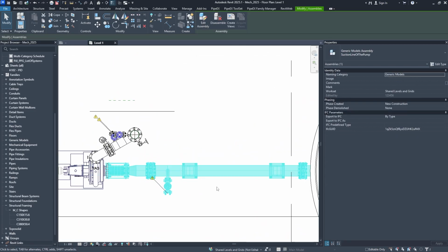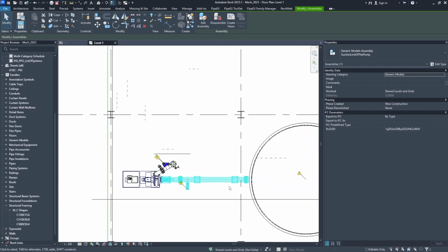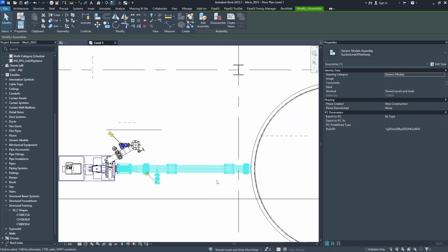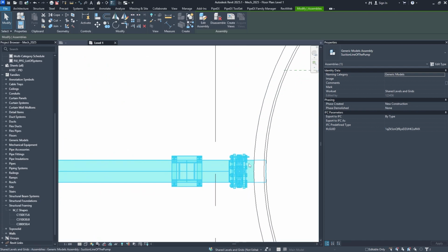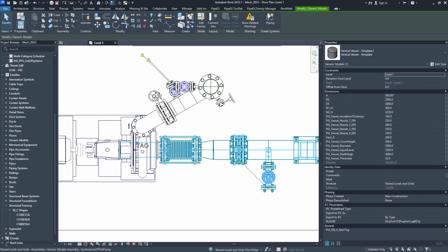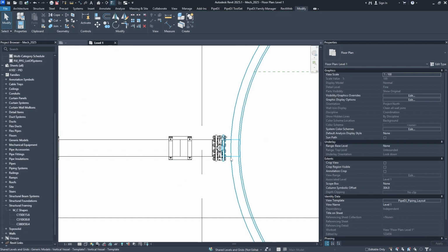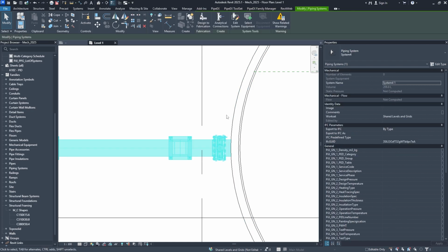Then what you can do for this assembly, you can add a reference, for example a comment, and you can add a remark on your piping layout, just not to show all the dimensions in this view. Because here you can use, for example, the nozzle of the equipment as a reference. Those nozzles have already been added to the assembly because, as you remember, we create nozzles as a shared family. So when we connect our piping to this shared family, it is also included.